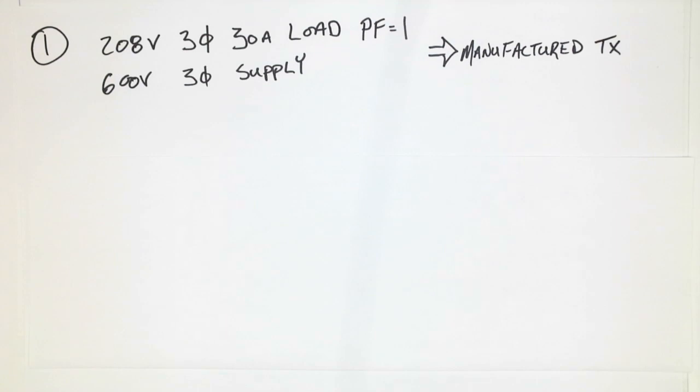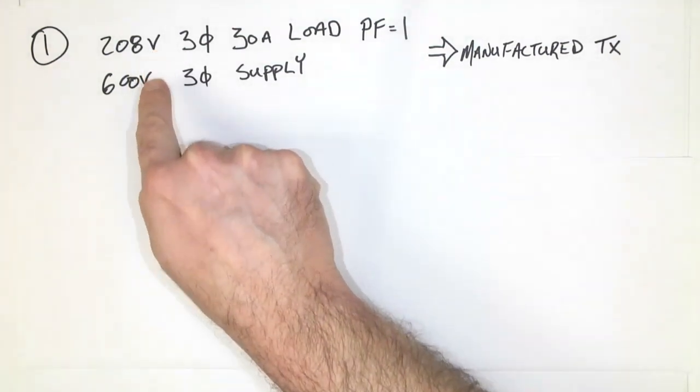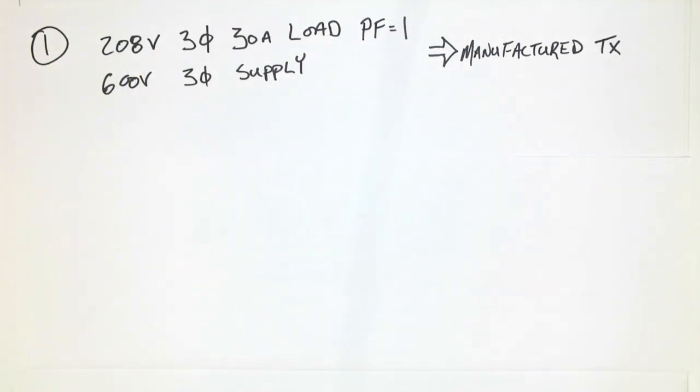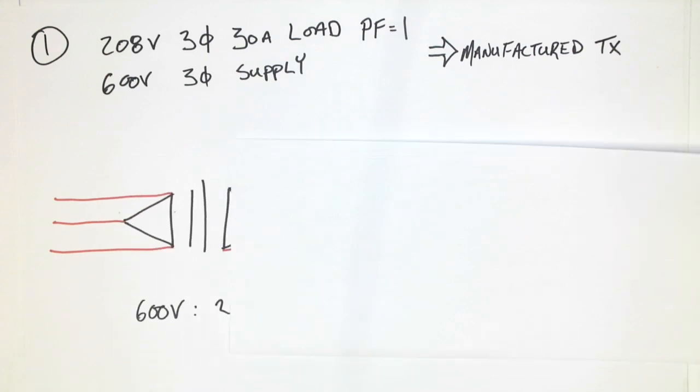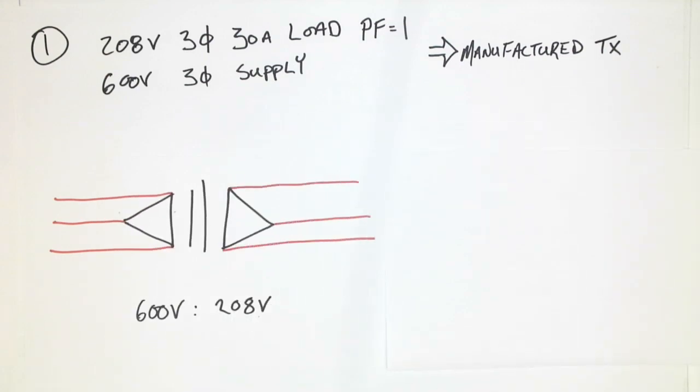Well, we've just got a straight voltage given here and a straight voltage given here. And what straight is in reference to is that there's only one voltage given. Whenever one voltage is given, it is always assumed that it is the line voltage value. And since there's only one voltage, we can safely assume that there is no need for phase values. Due to this, the most logical type of configuration will be a delta-delta.